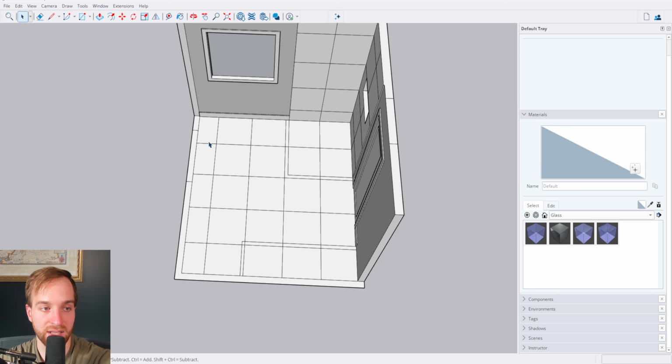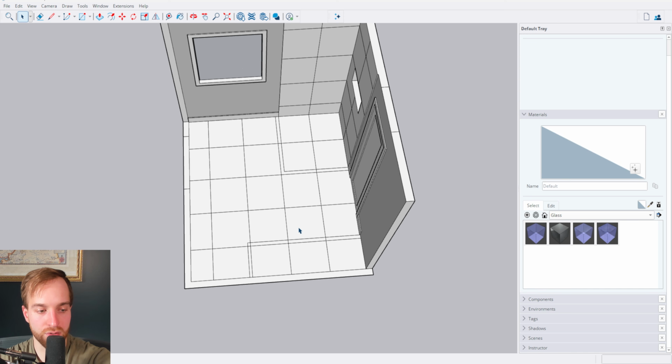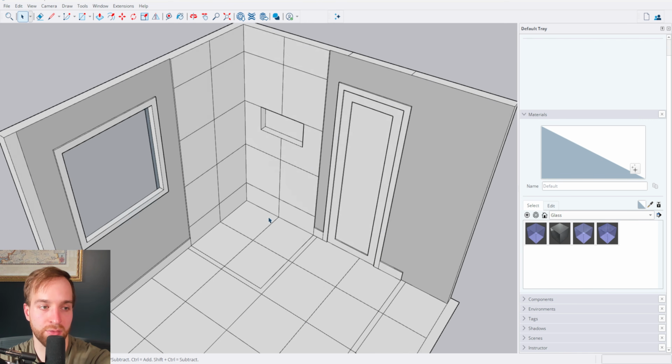Maybe instead of getting exactly 25 tiles, maybe I get 29 tiles, 28 tiles, 30 tiles, right? A lot of people will use 15 or 20% extra. When it's large format tile like this, I personally just prefer to count them. And then I'll typically, for a quantity like this, just add on a box extra. And then the same thing for the walls, right?